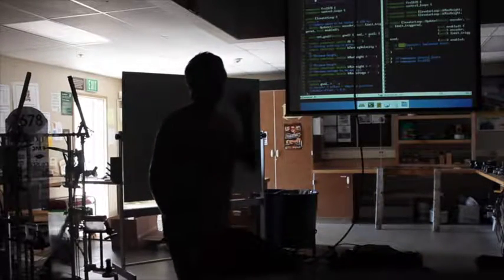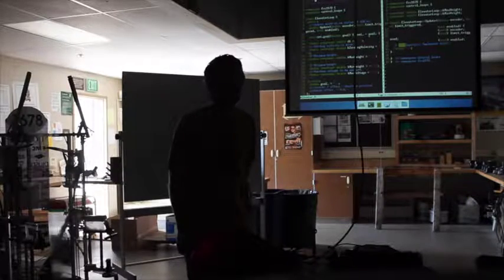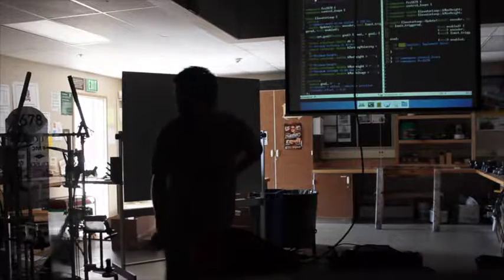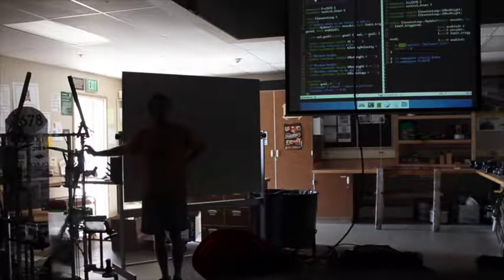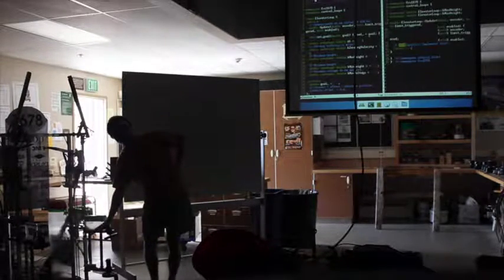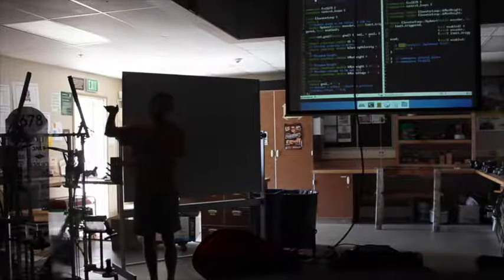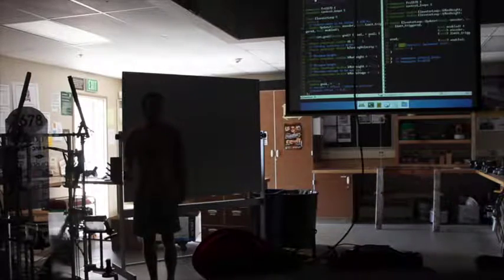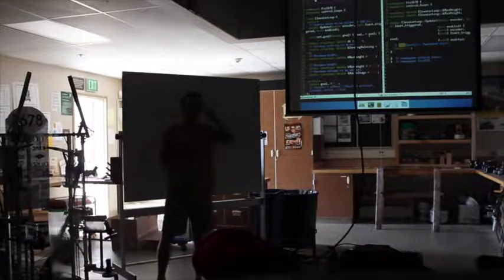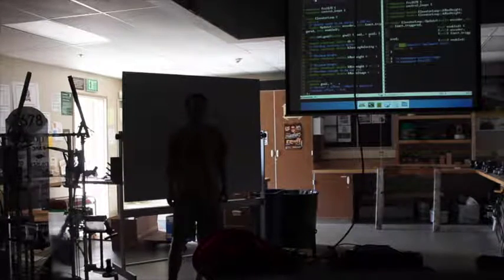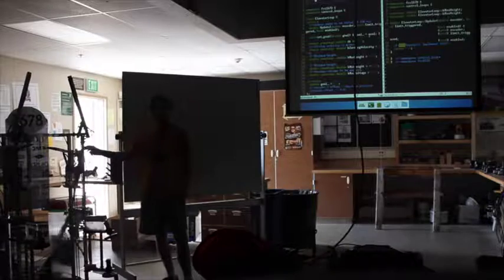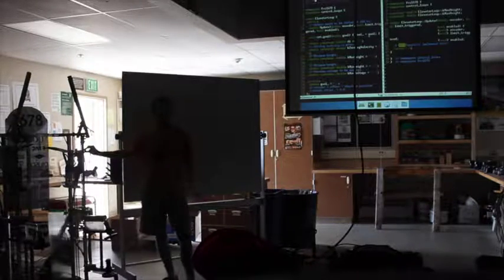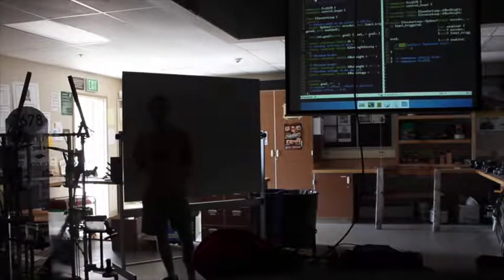One other question. So you said you're determining the offset. Why do you care where it started from? Because say we're going to try and stack boxes with this. We want to go down to a certain position so the box comes in, and then up to another position to make clearance. Right, but when you're trying to zero it, why do you care where you started? You say you're trying to determine the offset? Yes. We care because the encoder is going to read out 0 up here, and we want to know how to convert encoder units to real units.